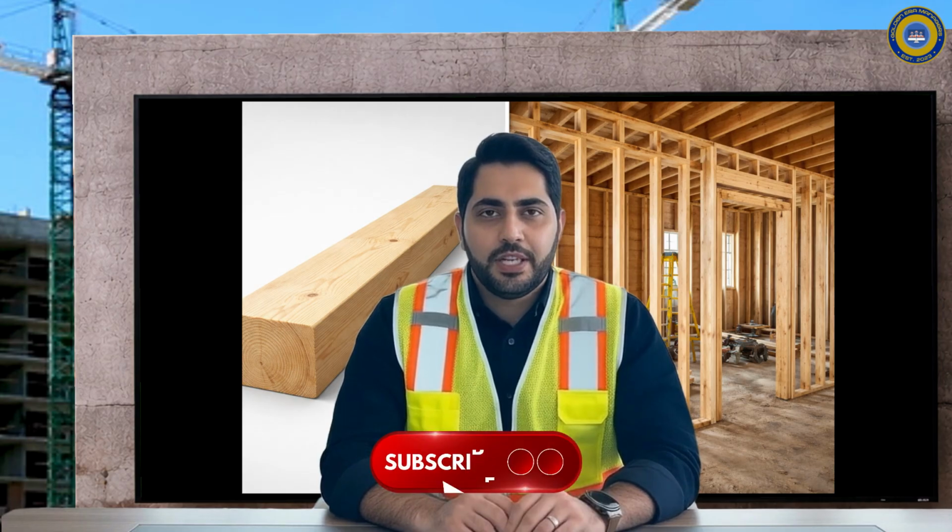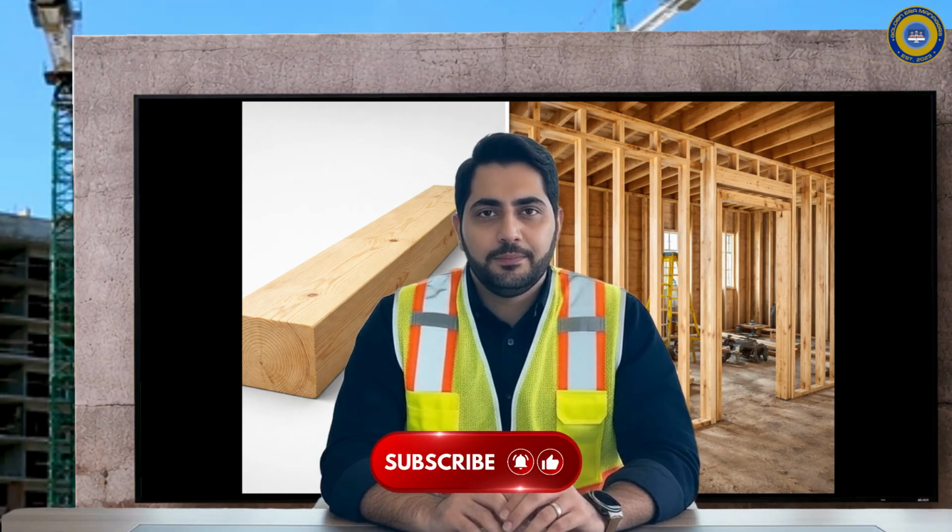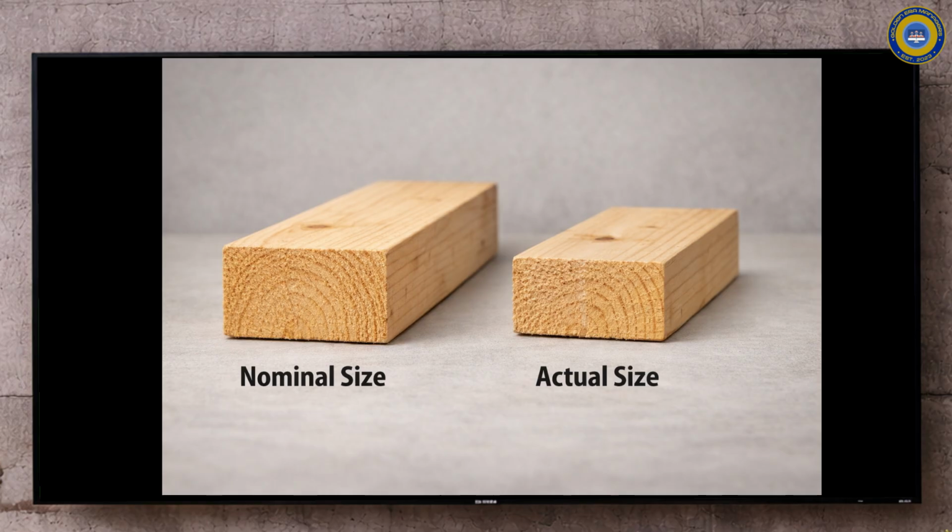Let's start at the foundation, with lumber sizing. The size printed on a piece of lumber is not its actual physical size. A 2x4 is not a measurement. It is a name, and confusing the two causes real problems in real buildings.